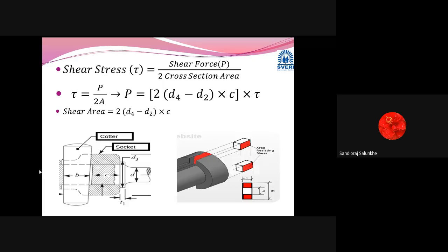Okay. So the thing is that this quarter is very strong, and as we apply tensile force in this direction, this quarter will get pulled out because this pivot is trying to pull this quarter with this force P. So if this area is weak, it will get sheared out, this upper and lower, because it is hollow.